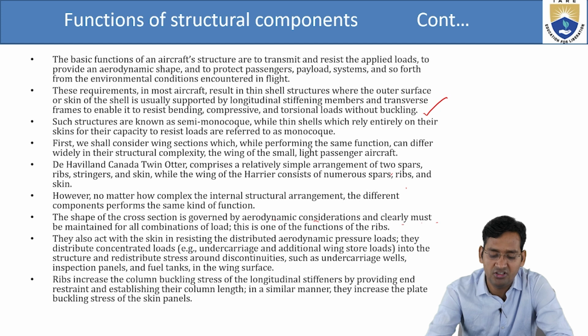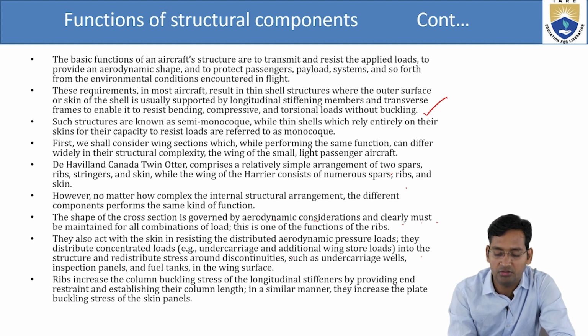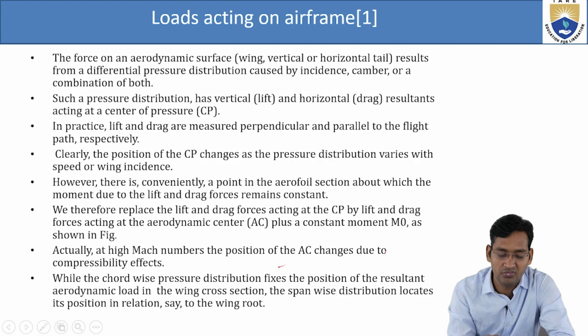They also assist the skin in resisting the distributed aerodynamic pressure. They distribute concentrated loads, e.g. undercarriage and additional wing store loads, into the structure, and redistribute stress around discontinuities such as undercarriage wells, inspection panels and fuel tanks in the wing area or wing surfaces.